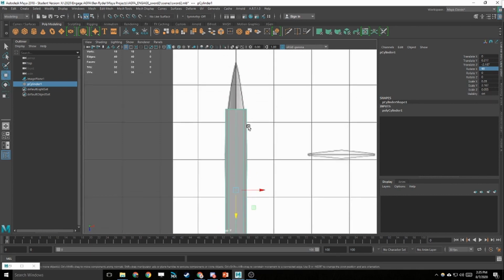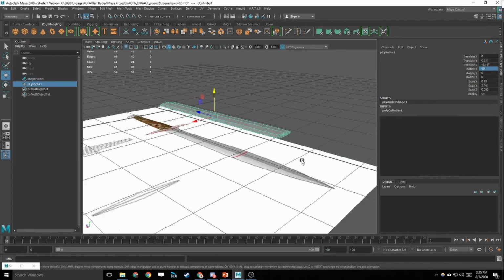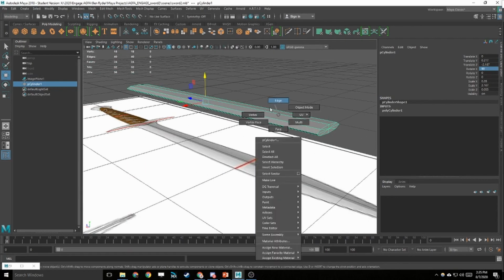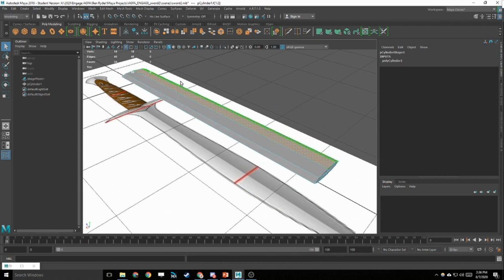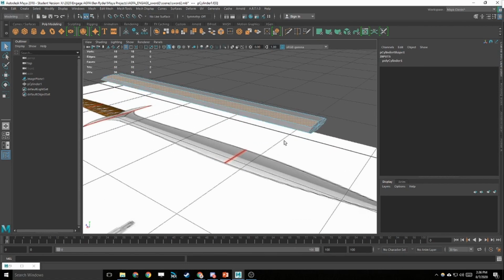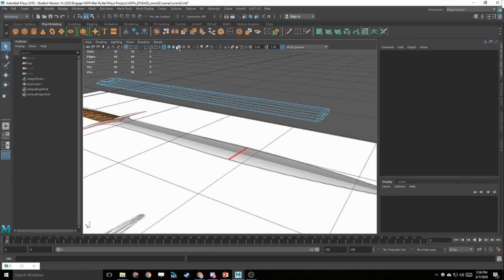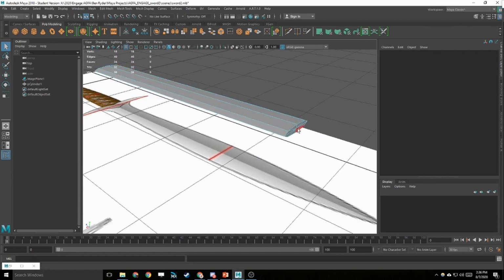Now to get this point, I'm going to start talking and looking a little bit at what makes up this mesh. Every 3D mesh, if I hold down the right mouse button, is made up of edges, vertices, and faces. Vertices are these little dots that exist here. Edges are the lines in between those dots, and faces or polys are the solid face that exists between them as a polygon that allows us to actually see this 3D shape. If we didn't have that, it wouldn't look very three-dimensional at all. We wouldn't have any light or materials bouncing off. It would just be dots and coordinates.